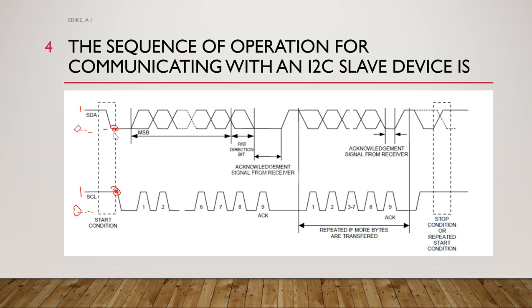The clock pulses are generated at the clock line for synchronizing the bit reception by the slave. In other words, he sends it in sequence, with a clock signal around it, so that it will flow in sequence until the intended device receives it.